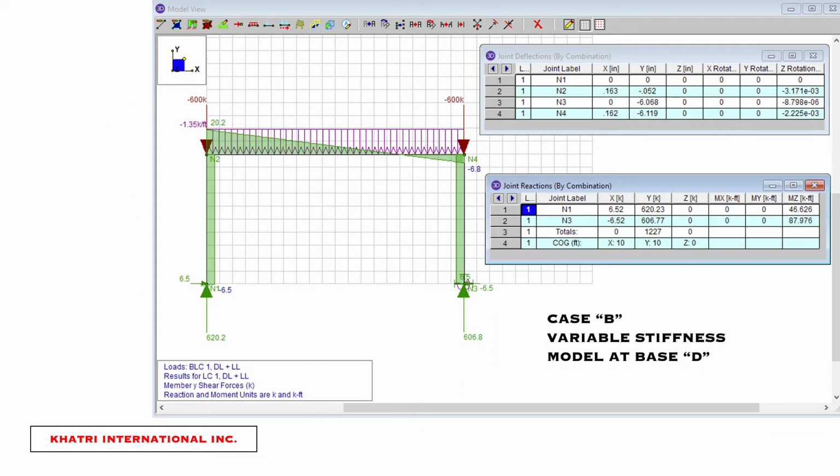In this slide, I have released the rotational stiffness, so now we're getting rotation at the joint D. I've softened the rotational spring, and you can see the deflection on the lower right, which is node number 4, or joint D, is up to 6 inches. And this has affected the stress distribution as well. You can see that it's very asymmetrical.